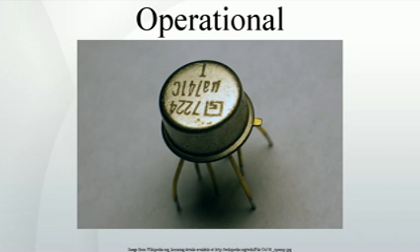Op-amp characteristics. Ideal op-amps. An ideal op-amp is usually considered to have the following properties. Infinite open-loop gain G equals Vout/Vin, infinite input impedance RIN, and so zero input current, zero input offset voltage, infinite voltage range available at the output, infinite bandwidth with zero phase shift and infinite slew rate, zero output impedance ROUT, zero noise, infinite common mode rejection ratio, CMRR, infinite power supply rejection ratio.